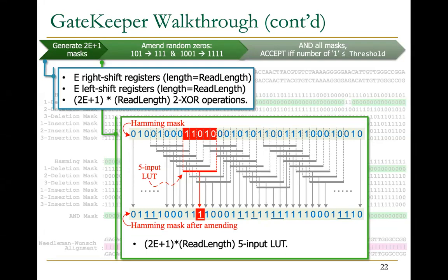For us, we were aiming to change only a single 0 or 2 zeros. So how many inputs do we need for that lookup table? This is a very important metric to choose the appropriate FPGA so that we don't double the resource utilization. If the number of inputs for the lookup table is less than or equal to the number you have in the FPGA, then that is the ideal utilization of the FPGA resources. If you have more than that, then you directly double the number of lookup tables, even if they are underutilized.